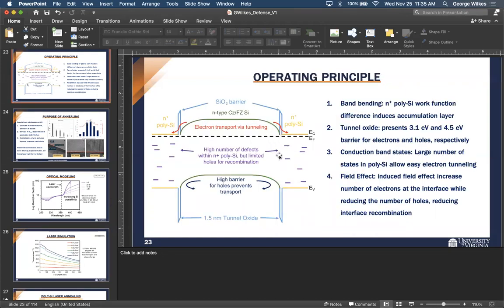Because sometimes these dopants will diffuse from the highly doped region into your active medium, right? It's a bit of a balancing act to prevent that. I want as much activation as possible, as close to the surface as possible, while preventing any dopant diffusion into the bulk. I see. Yeah.